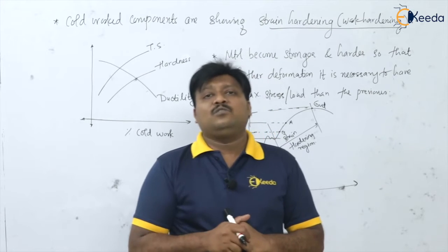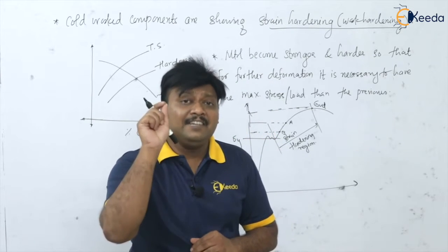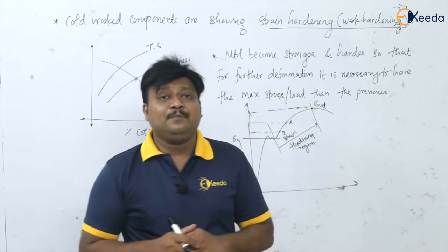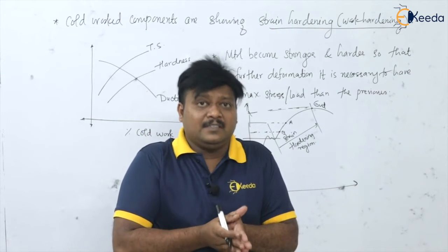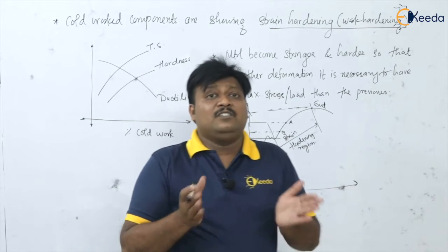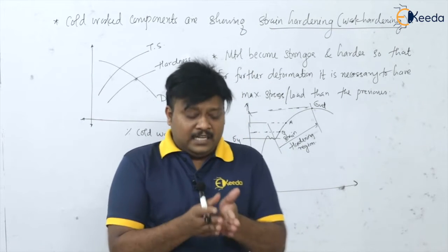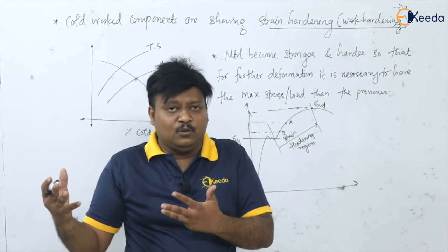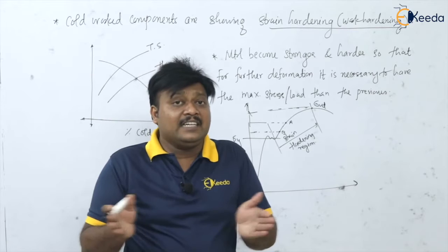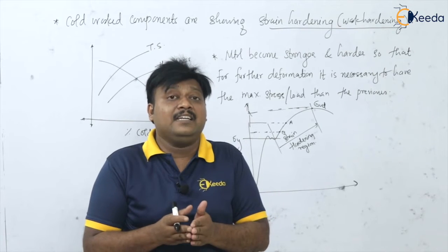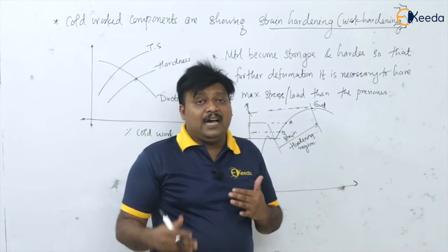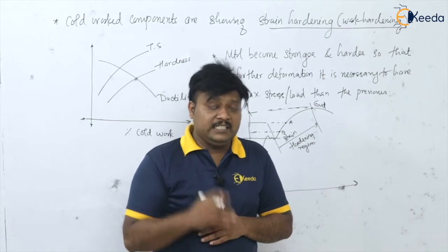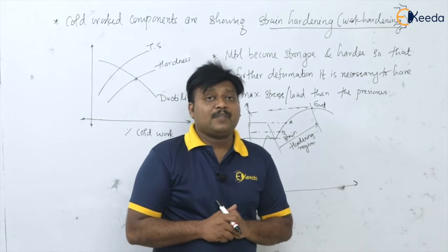So annealing, what is in annealing here? This annealing is having 3 steps. Which is the first step? That is recovery, that is simply the stress relief annealing, isn't it? After recovery, at quite higher temperatures and for higher holding time, we are having the recrystallization, and after recrystallization we are having the grain growth. These 3 steps we are having for this annealing.